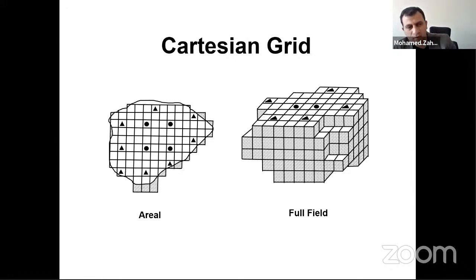What does finite difference mean? It means that for a certain point, to calculate the pressure at this point, I need the next point's pressure and the previous point's pressure. So how do I solve this? We are building a grid to give you the finite difference, so that you can calculate the pressure from the pressure in the next grid and the previous grid.